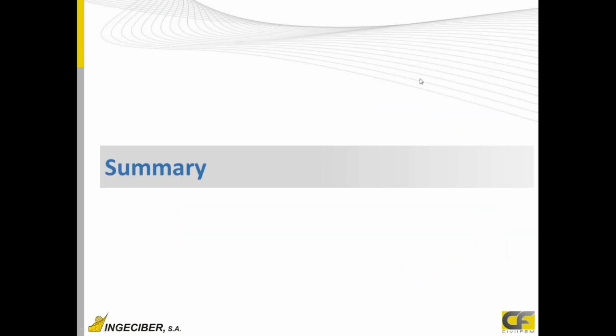Well, these are all the examples we wanted to show today. For future webinars, we will see consolidation material models, to solve a mix between Cam clay and seepage analysis, where the water table affects the consolidation problems, to calculate transient analysis and consolidation over time with these material models. And we will see other material models different from Cam clay, such as Mohr-Coulomb, that we have used for this model.